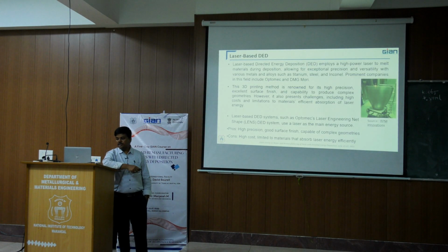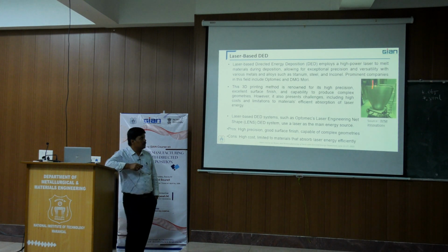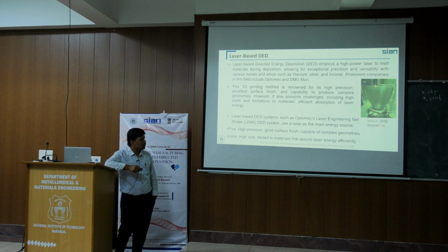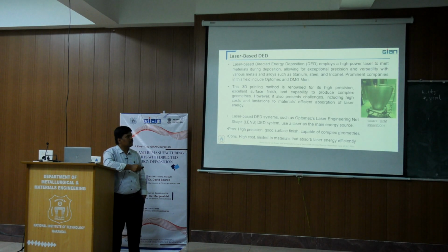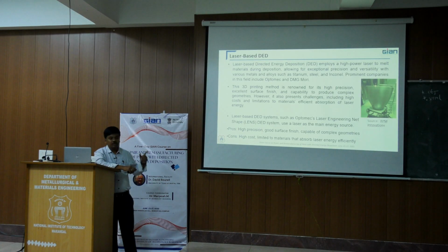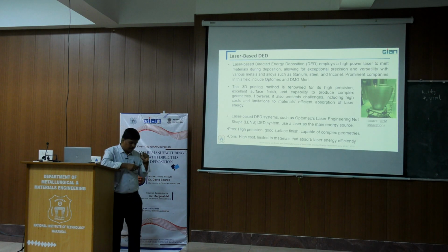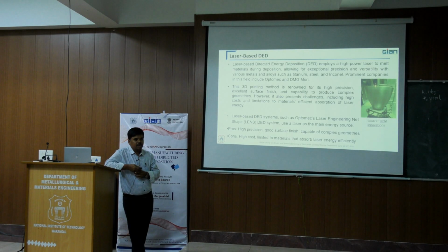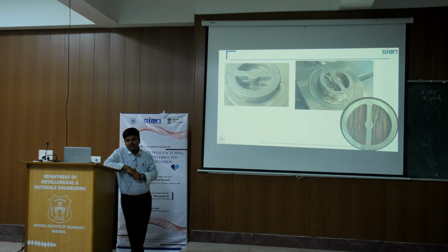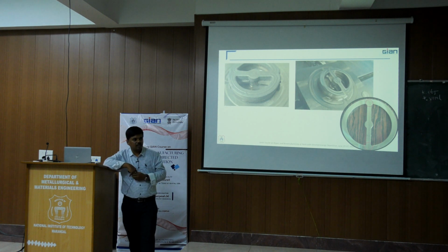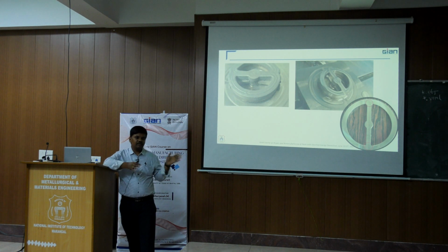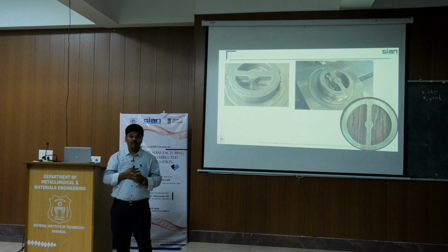That's why, if you see, LENS or maybe the RPM industries have made some kind of aerospace part with the LENS, and it is most cost effective, with limited materials which we are able to fabricate. And with respect to this laser based, even in our concept laser we have done a lot of studies to fabricate near net shape components. One we have tried with this injector head. This was worn out in some of the aerospace parts. They were trying to repair it, how we can repair it. But initially we tried with the TIG welding process. Can we repair it?